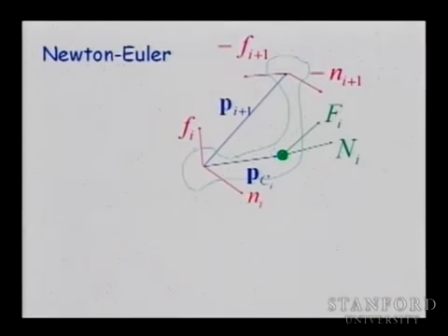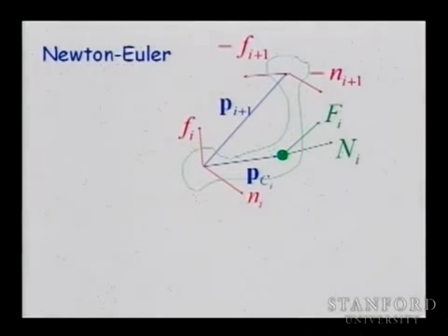That is a very different way than the way Newton and Euler formalized the dynamics, which relies on the fact that we take each of these rigid bodies and connect them through reaction forces. If you take all the links and remove the joints, you substitute the removal of the joint with reaction forces, and then you can study all these reaction forces and try to find the relationship between forces and acceleration.